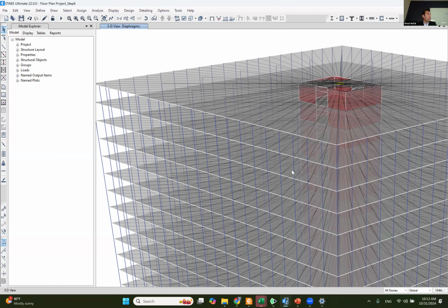Then I'm going to uncheck the eccentricity check. When we do design, we need to keep the eccentricity, but right now we are doing analysis. We only do parametric studies, so I don't want to get into more details with the design. But when we design a real building, you have to include eccentricity X and Y. You have to include everything. Actually, when we do analysis, you might end up having 100 load combinations on the building because you want to take everything into account. All right.